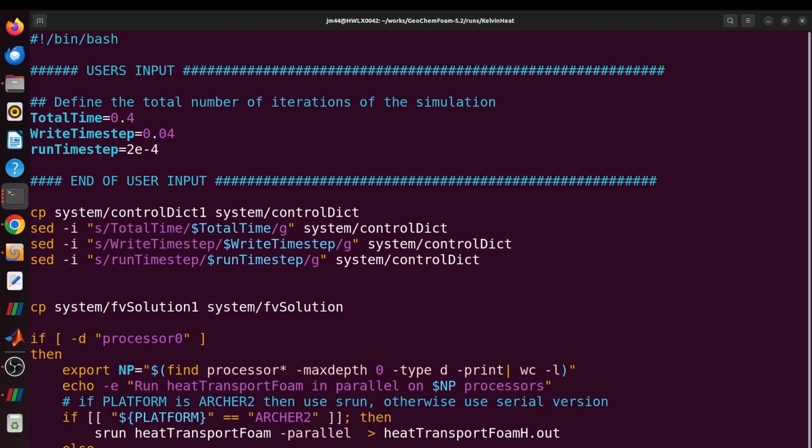And we need to choose how long to run the simulation, when to stop for a report, and what time step to use. And because the solid conductivity is so high, the thermal response will be fast, so I will just run this for 0.1 second. We will write every 0.02 seconds, so we get 5 steps.